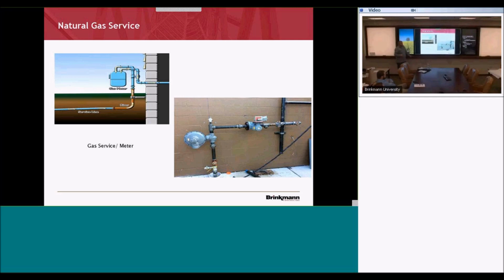And then also, after the meter, sometimes in certain seismic ratings, they're going to require a flex line that goes from the meter through the building. So when we come through here, this might be a flex line, or there might be a flex piece from there to there. That's in case there's any shift, it doesn't just shear off your natural gas. Some of them require sleeves with so much room in them. At Fort Leonard Wood, we had a flex line that had to go in there.